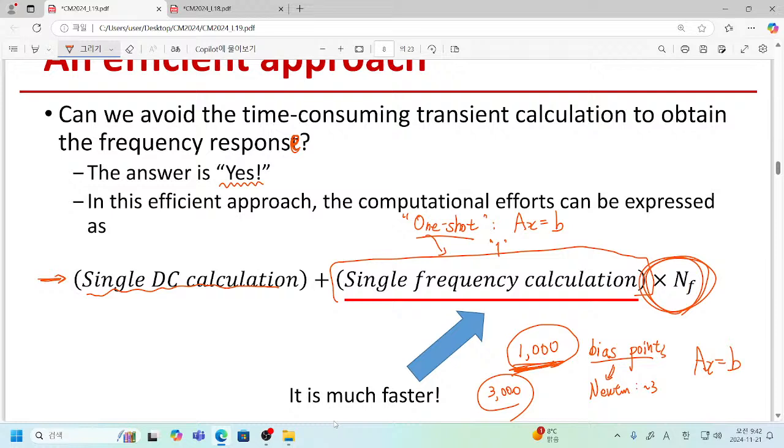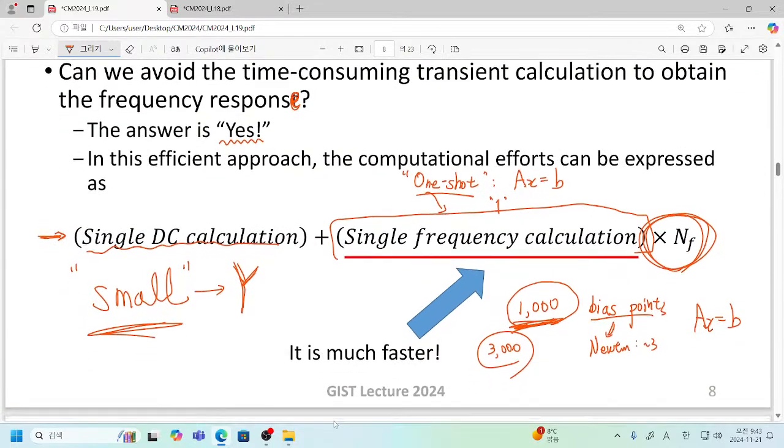Of course, please note that I'm not cheating at all, and the magic comes from what? The magic comes from our assumption, small amplitude. Without this small amplitude, our great enhancement in efficiency cannot be achieved. Please note that there is no free lunch. This is obtained by sacrificing the generality of our calculation. However, fortunately, our parameter of interest, this Y parameter, by its own definition, always assumes the smallness of the input voltage excitation. So it is completely okay to assume this small input voltage excitation.